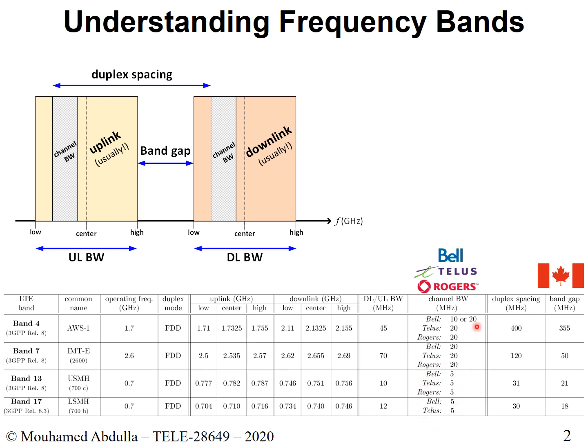But in general, you want the higher frequency. That's always better for you. So that's the channel bandwidth. Okay, so channel bandwidth, just be mindful, it will not take the entire width of the frequencies that you have for downlink or for the uplink. It's only a slice of it. Only a slice of it.